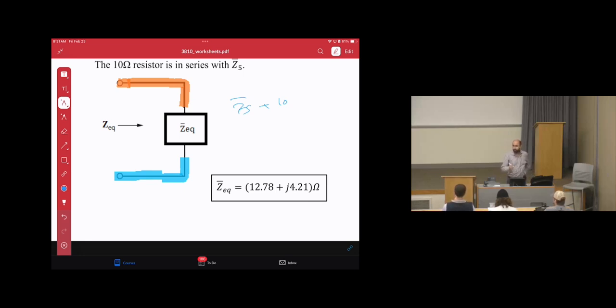Okay? So in summary, in solving the circuits, finding equivalent impedance is the same as finding equivalent resistance. The difference is, first, convert everything to ohms. The second difference is we are dealing with complex numbers. Otherwise, it's the same: labeling the nodes, series, parallel, short circuit, etc. The same techniques that we've seen before. Any question?